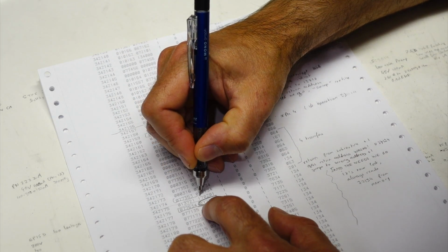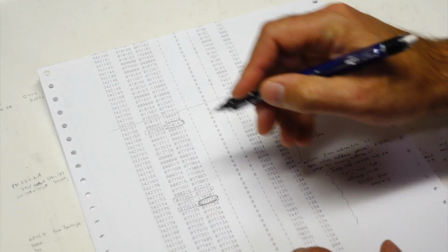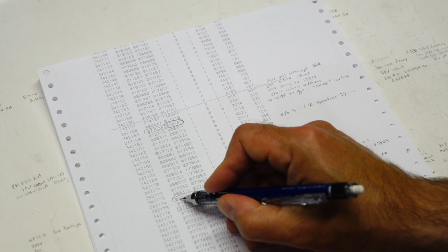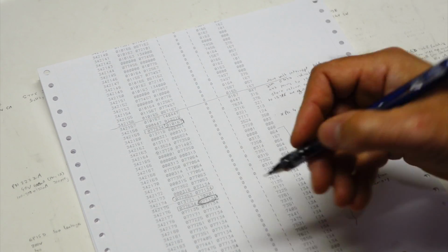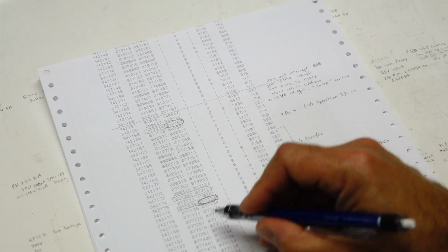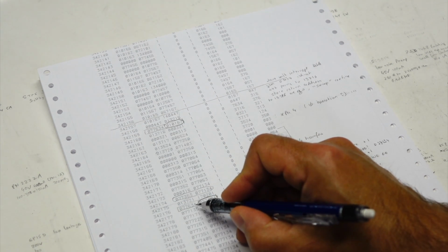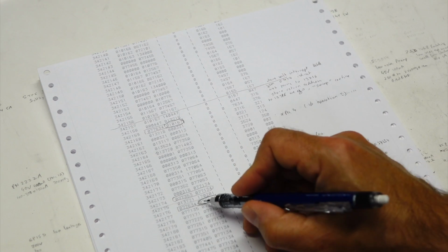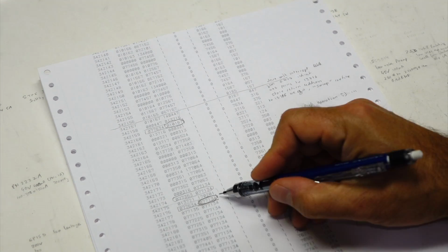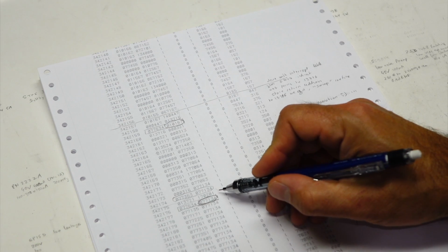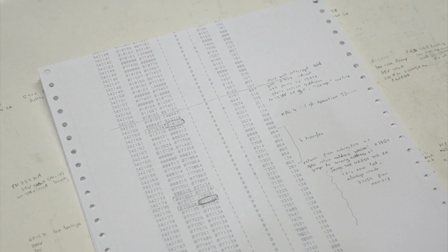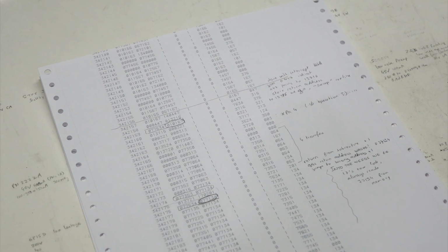Before it accesses this, it tried to write 077134 to address 77353, and of course that went into address RAM 0. And then when it reads it back here, trying to read from 77634, it reads it back from 0 and retrieves exactly that. I think my theory is right. Refresh is working. It didn't lose it with refresh. It just gets all mangled up because we have only 1 word of address that's alive in our whole memory here. We can't access the rest.